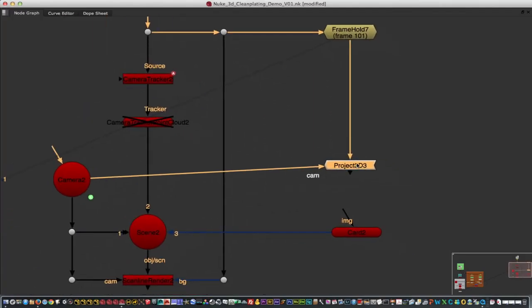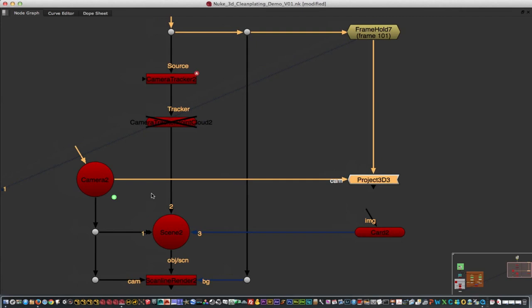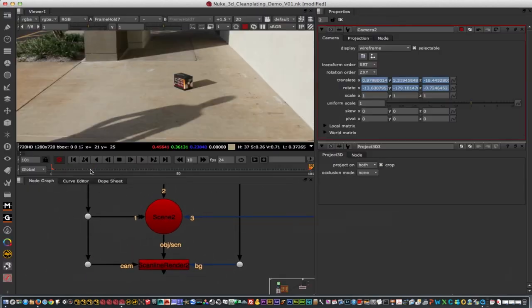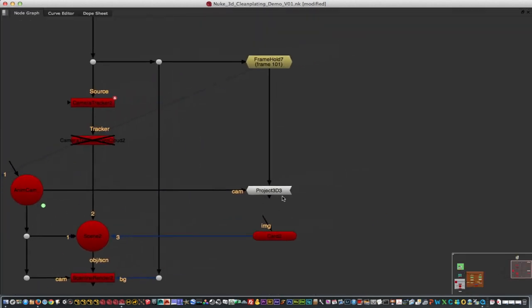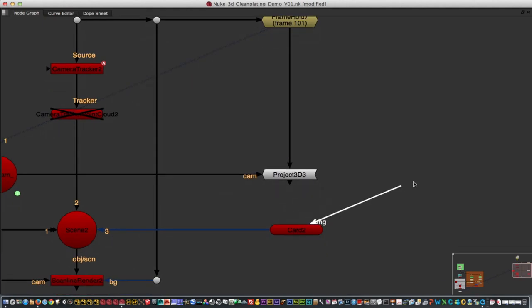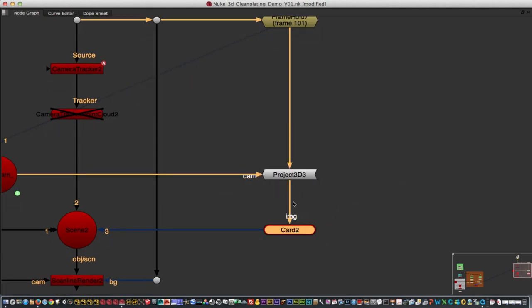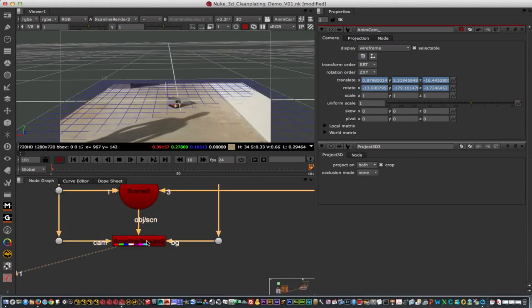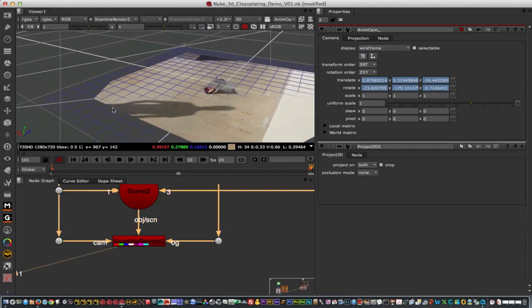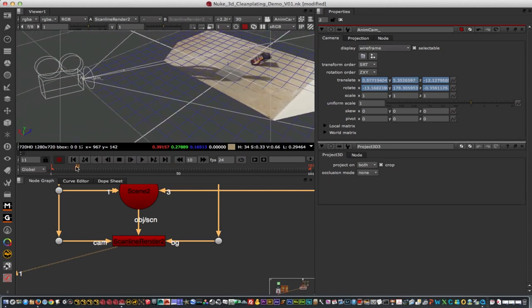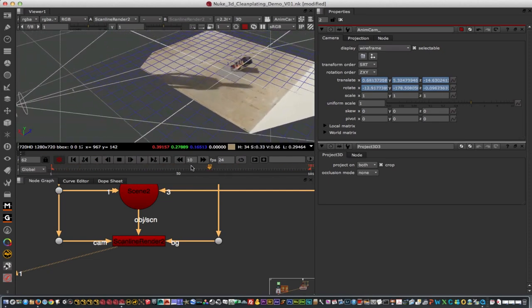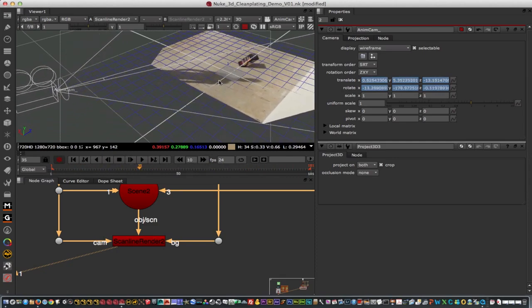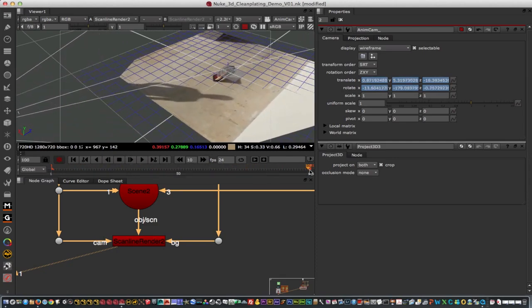So it's camera number 2, or in this case whatever camera version you have. If it's 1, it's 1. I like to rename this animation camera, so I name it anim cam, so that way I know it's my animation camera. And now we're going to connect that to the image input of the card. So what is going to happen now, if I go to my 3D view and I look at my scanline render, so hit 1 on your scanline render, you see that now the camera is projecting the information through into our card. But the problem is that the actual information is moving.